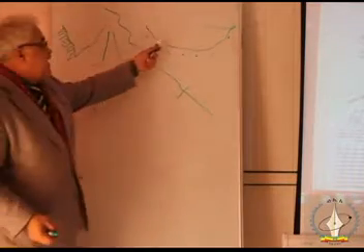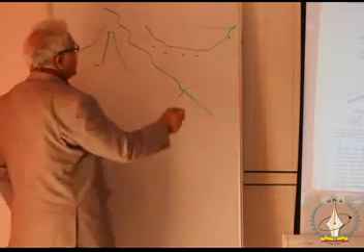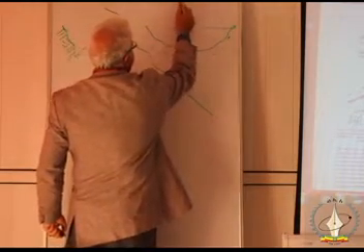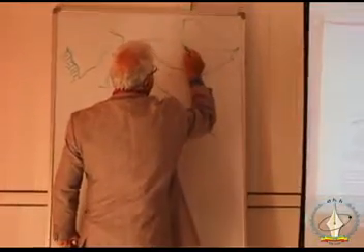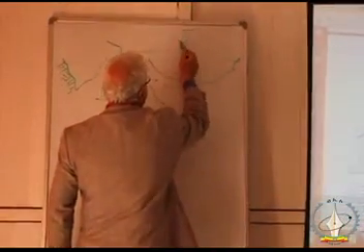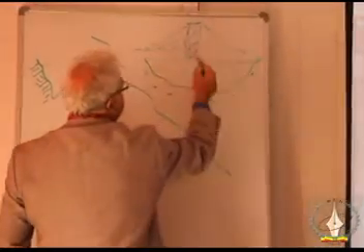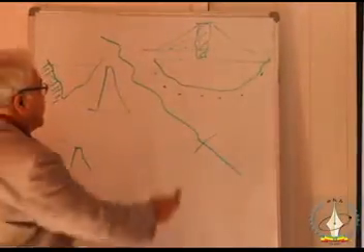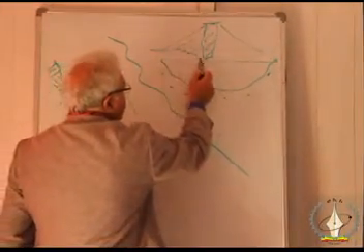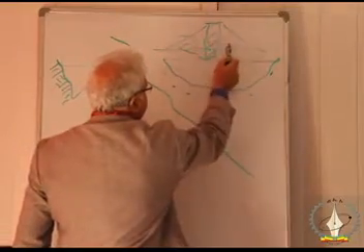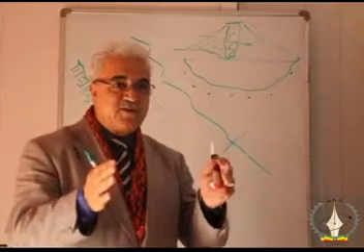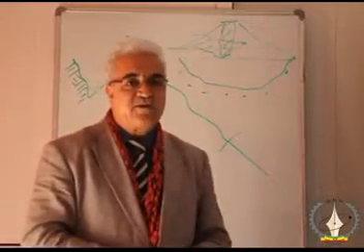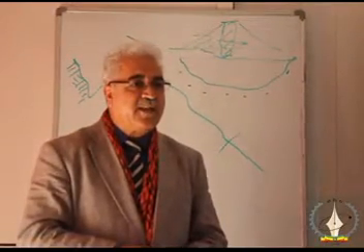So here it would be better if you design an earth-filled dam like this, where you may use a clay core in between and then some other material here and there, and if there is water seeping through, water can also seep through the dam itself. The only thing is it needs to be controlled. It has to be under control, and that is okay.